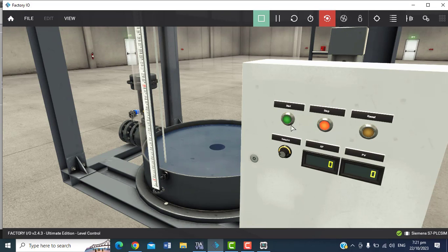If I press red, it will stop the green, and I will show that the thing doesn't stop. Then if I press start again, it doesn't work until I reset them. If I reset them, then I can press this one. So this is how they work, but this one is just with ladder logic. Yes, we can do this with every other programming language, but what I just showed you is ladder logic.